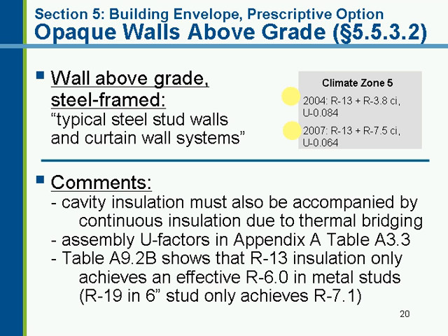Now, the key thing here, metal studs, as you know if you've ever touched a metal frame window in the winter, are a great conductor of heat. And the thermal bridging is a big problem, and so you need this continuous insulation to break that thermal bridging. If you look in some of the tables at the end of Chapter 9, there's other good reference material there.